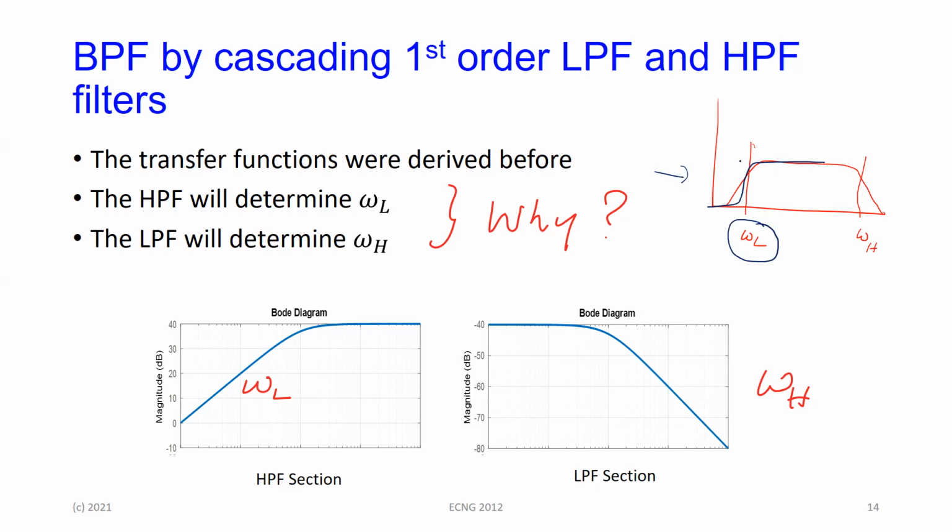And then whatever is passing here now, when it reaches a particular cutoff frequency, we want it to reject everything higher than that. So this is the low pass characteristic here. But this also is the higher cutoff frequency for the bandpass. So in other words, the lower frequency is determined by the high pass filter. The higher frequency is determined by the low pass filter. Clear? Make sure you're following it.